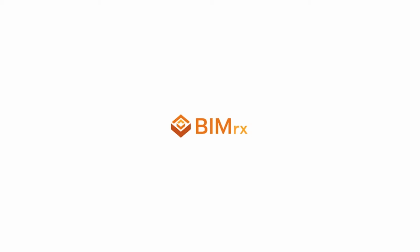All right. So BIMrx is Microdesk's growing suite of Revit tools, whose earliest feature round trips information from a BIM model to Excel and back again. These tools can be used to quickly put information into the hands of non-Revit users and put to use Excel's powerful formulas and conditional tools to help designers edit their models. For example, we can perform quality assurance checks, find and replace data, convert parameters to uppercase, import information from third-party sources, matching it to our tags, perform calculations, or takeoffs.